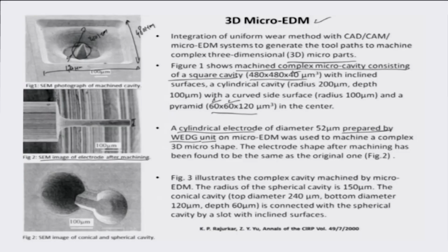I think I illustrated earlier that with another kind of identical wire assisted ECM process, we had produced about 2 microns of tip size. In this particular case, although the tip size is slightly higher, about 5.2 micrometer, it still is a very high improvement over the other machining processes which exist.